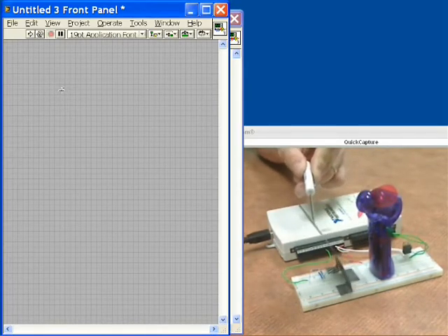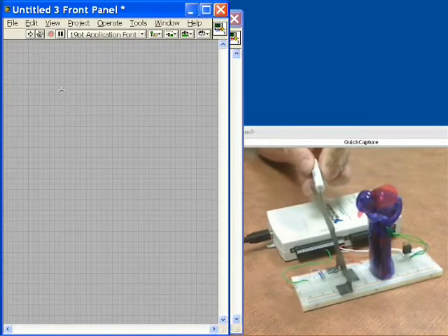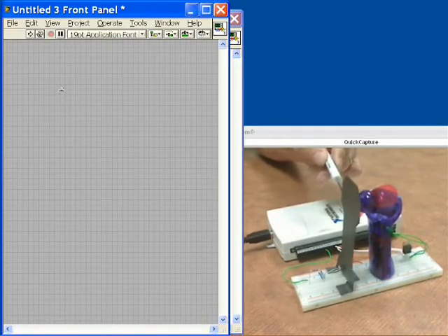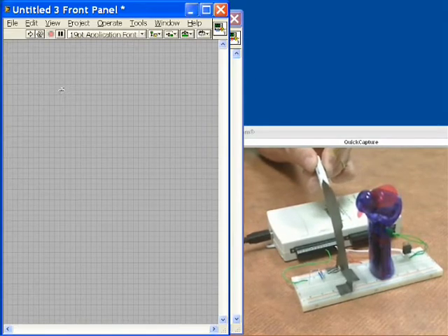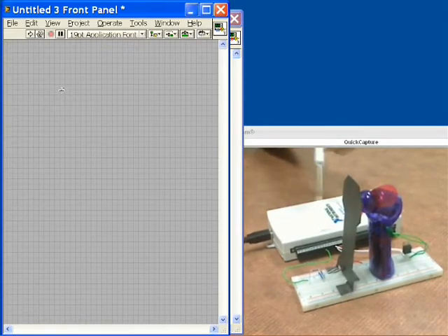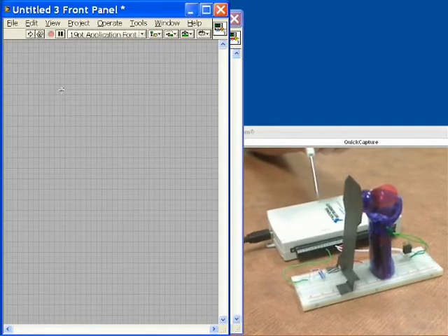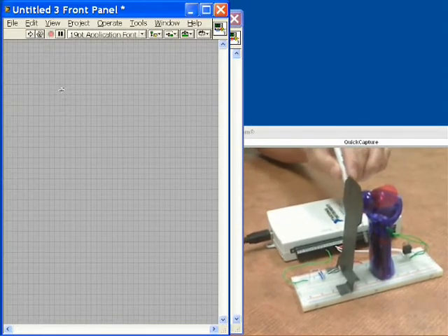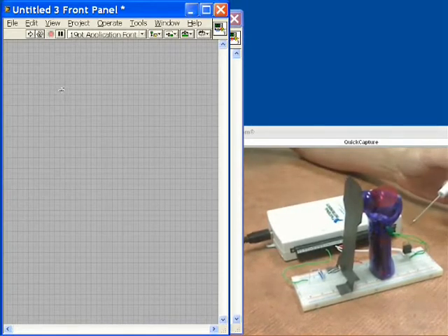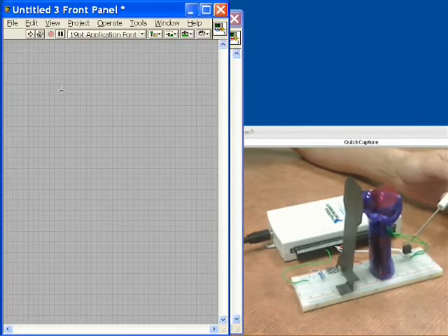As the deflector moves back, we're going to be measuring the position of that, and we'll be doing closed loop control to maintain the position of the deflector at positions that we select. So the way the setup is with the USB 6211, we're taking an analog output channel, and over here we're coming into a power transistor. It would be nice if we could just drive this directly with the analog output, but these bus power devices of course don't have that kind of power.